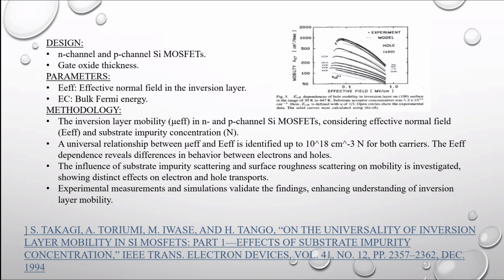The design of the study involves investigating the inversion layer mobility in both N-channel and P-channel silicon metal oxide semiconductor field effect transistor MOSFETs. The researchers specifically focus on the effective normal field and substrate impurity concentration as the main parameters affecting the mobility. The gate oxide thickness is also considered as an important factor in the design. The methodology used in this study